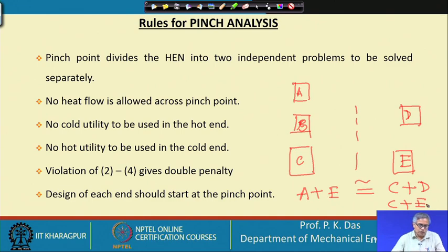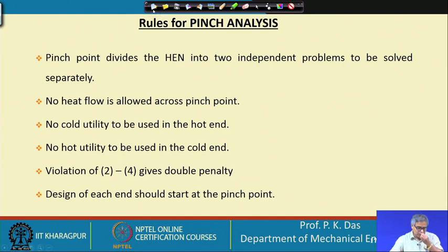Okay. So, this is one very important aspect of pinch analysis. No heat flow is allowed across the pinch point. This is a very important thing, that once we identify the pinch point, by mistake, by wrong design, by some sort of fancy design, we should not allow any heat to be transferred from one side of the pinch to the other side. No cold utility to be used in the hot end.